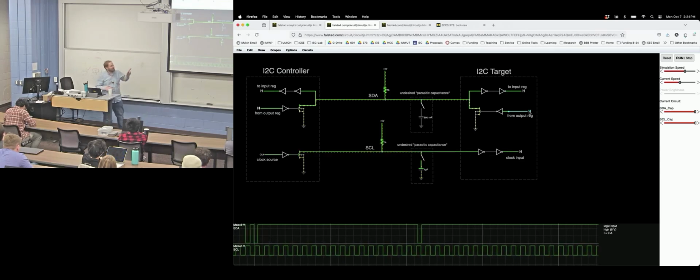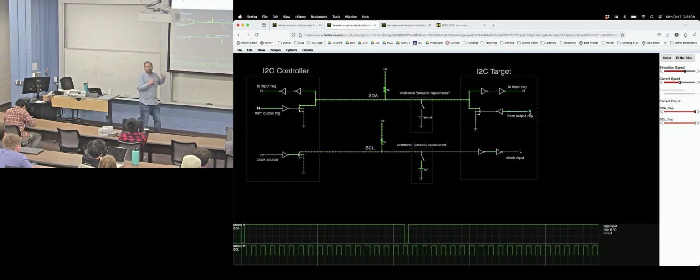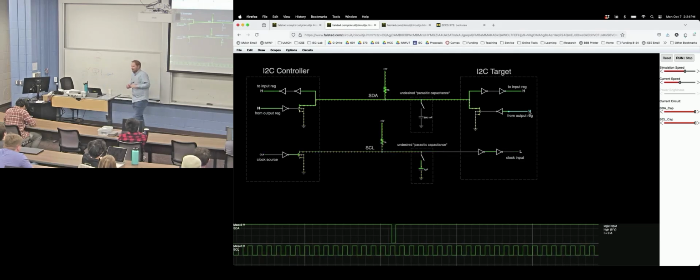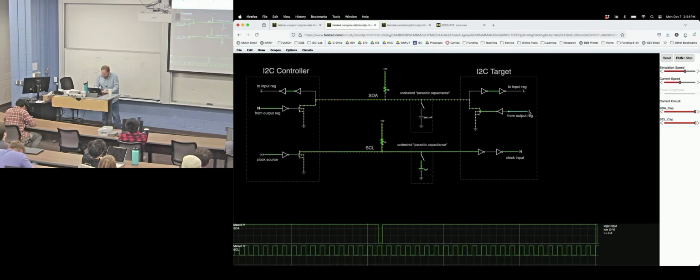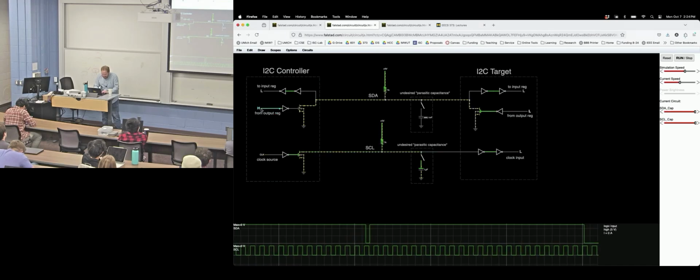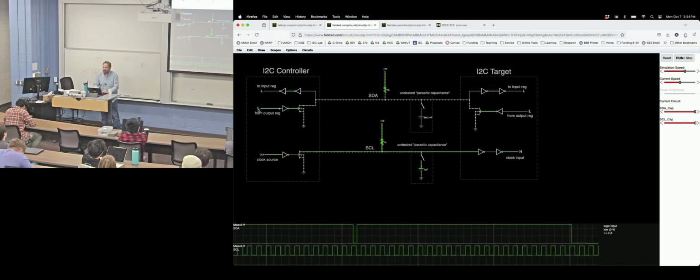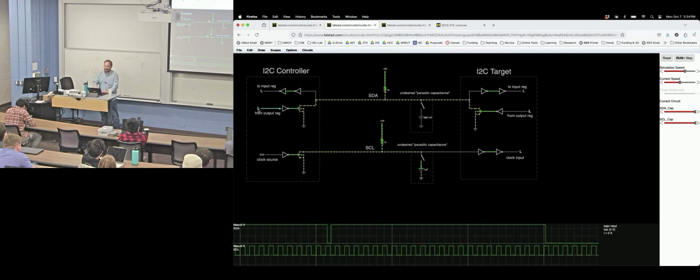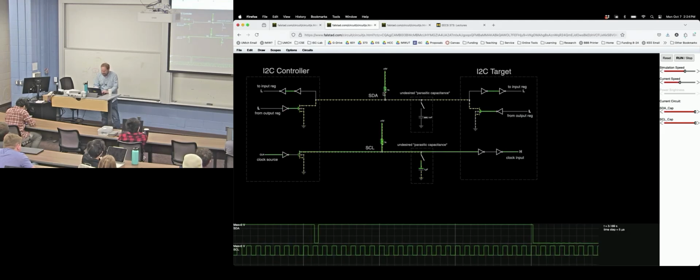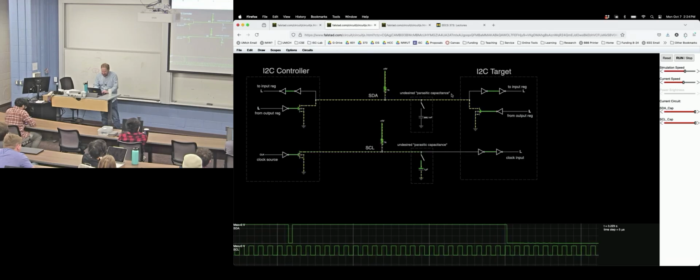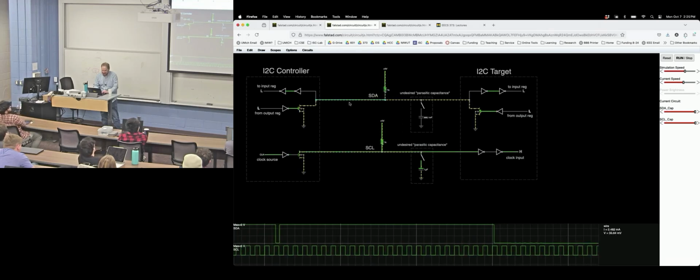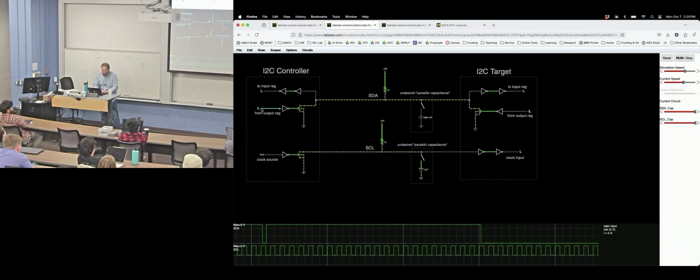Here, one of the reasons they have the pull-up line is it's impossible to burn things out because you can both go, I can pull this low and I can pull this high as much as I want, but it's still low, right? But it didn't cause a problem. I'm still sinking this current. Here, let's increase the current simulation speed. I'm still dumping this current to ground, but I haven't blown anything up.